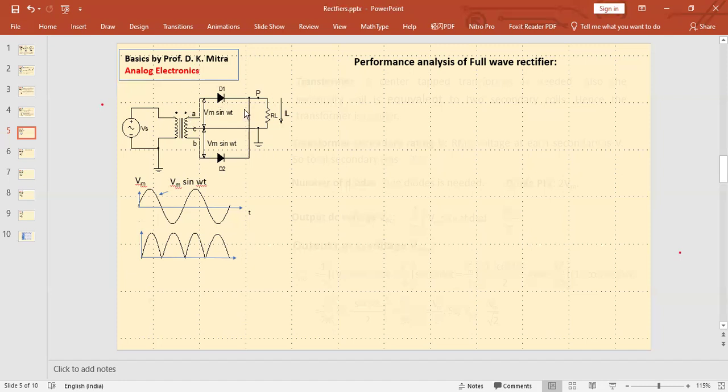Slide, you see a picture of the full-wave rectifier where there are two secondaries, and each secondary has a peak voltage of Vm. In both half cycles of the primary, the current flows through the load in the same direction. So when this is the primary waveform, the secondary waveform is like this. Each half cycle becomes a positive half cycle. Okay, we know that. Now let's see how it performs.